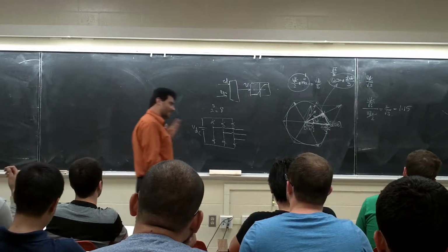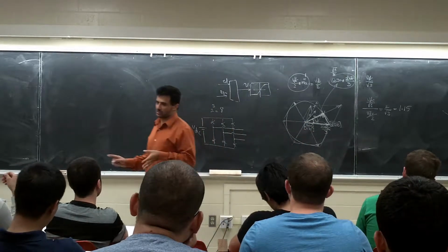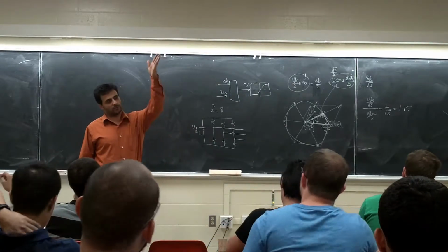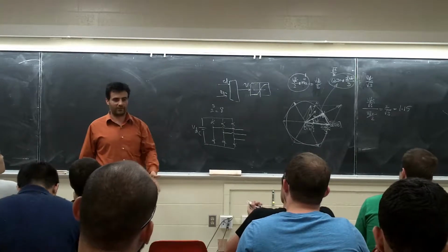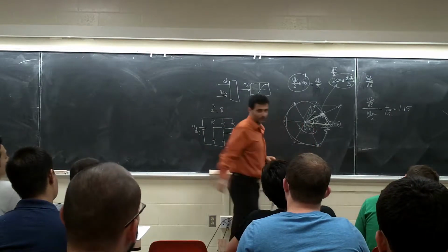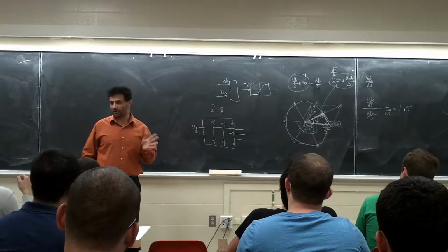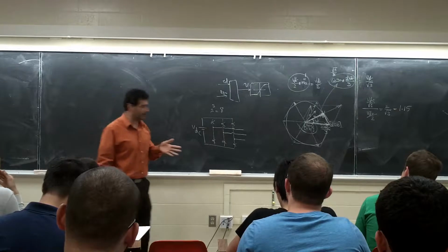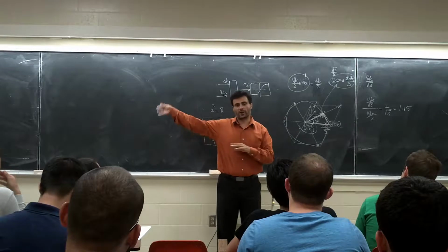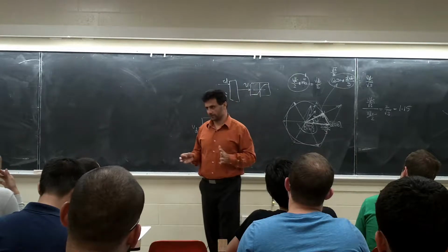But what we did, the good thing about the method I explained, we don't have any control on the switching algorithm. As soon as the control is more than the triangle, on, less, off, that's it. Here, with these two vectors, you can go unsymmetric. It's up to you how much you want to read about this one. If we go completely symmetric on switching, it's going to be like what we talked about. But you don't have to be symmetric on the switching. You can make it unsymmetric.